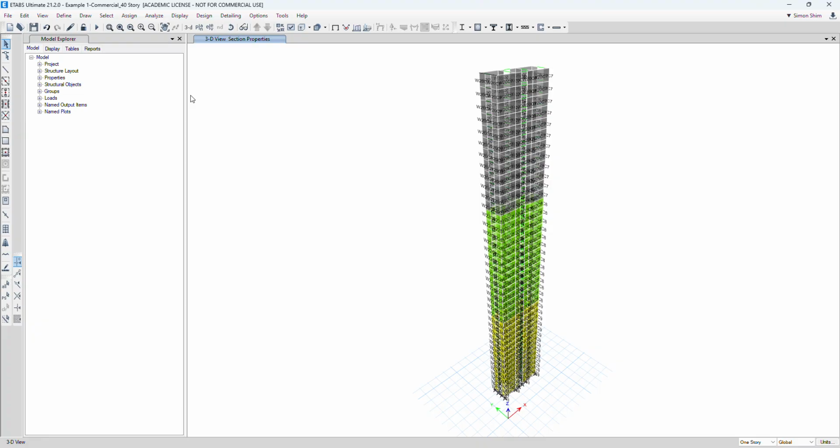But you need to make sure using XY or YZ plane, aperture 0. So you should be able to select at one shot, one selection, right? Yeah, make sure. Because we have multiple walls in 3D, so selection is really cumbersome. So once you set it up this way,